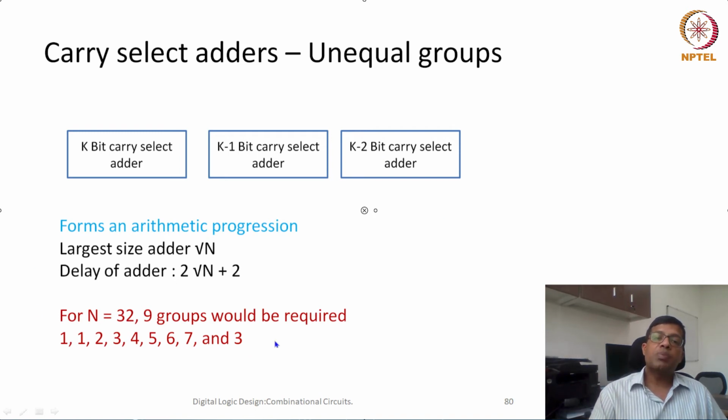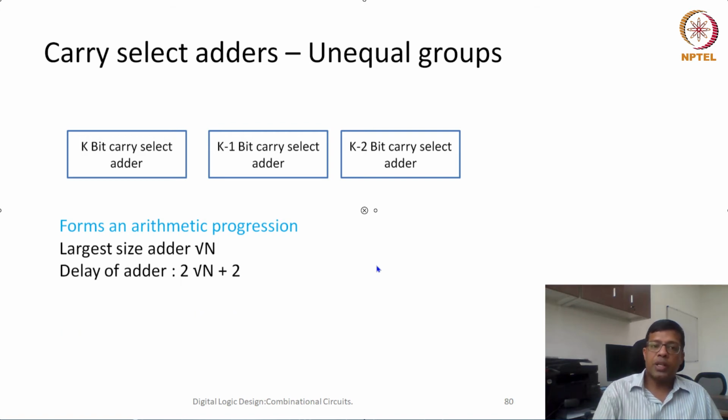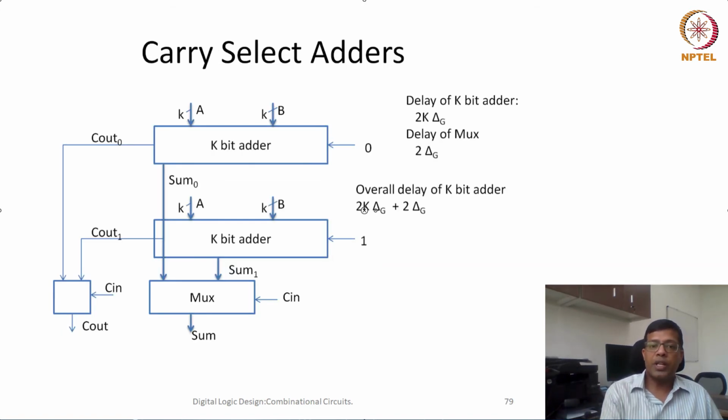So this particular type of adder, although it looks a little orthodox, in that we are doing computation twice, seems to be very effective, because by the time we are doing computation, some other part is calculating whatever we were dependent on. Here we were dependent on C in, so this C in can be computed in parallel, and we are duplicating the hardware and doing it twice.